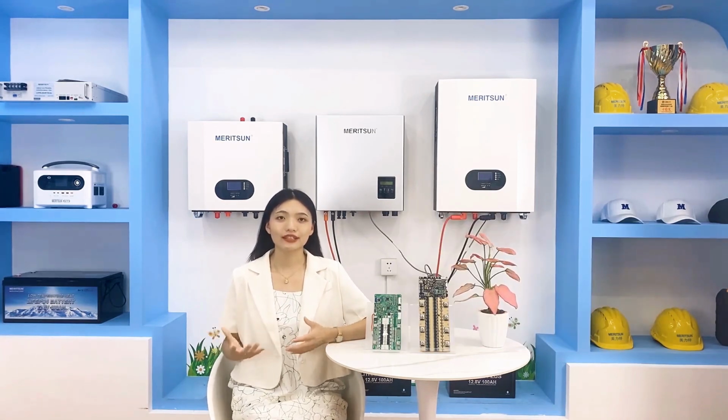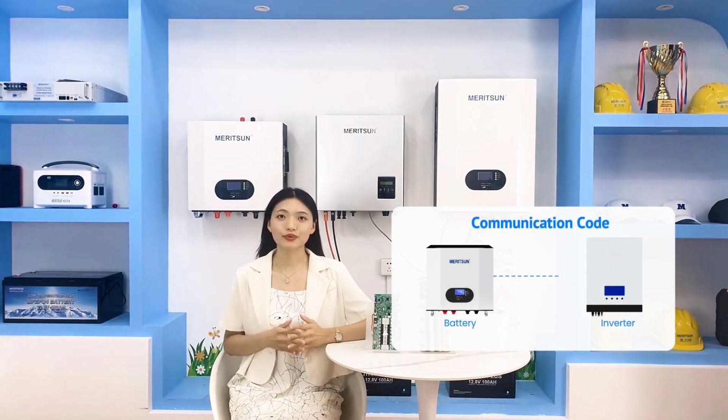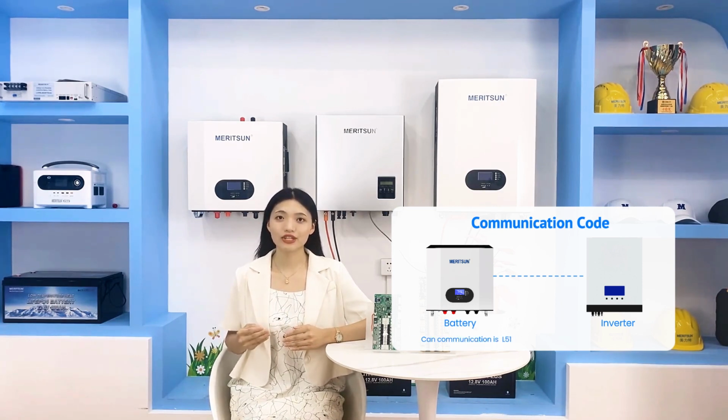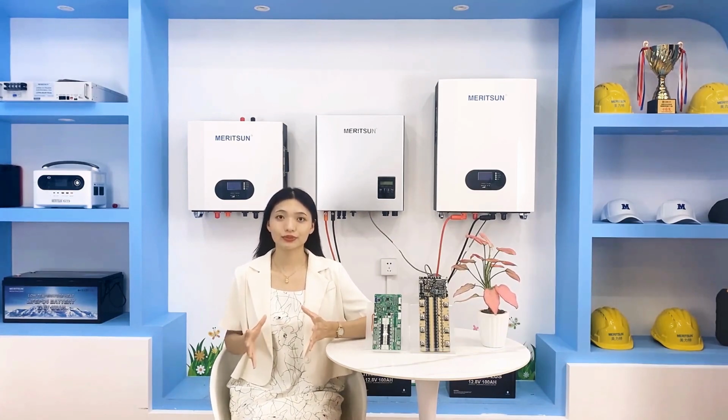Sometimes we will face another situation where the inverter can communicate with the batteries on both the CAN and RS485 communication ports. You should know that the communication code will be different. For example, for the communication between a MeritSun battery and a Growatt inverter, the communication code for the CAN communication port is L51, and the communication code for the RS485 communication port is L01. This is quite common and should be paid attention to.